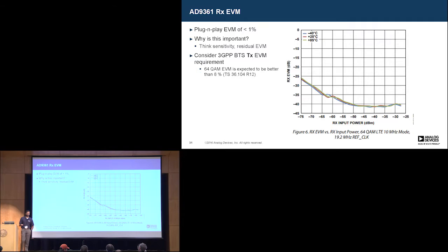The 3GPP specs, for example, call for a reference sensitivity level for different types of base stations. So for, let's say, 20 megahertz LTE, you have like minus 101.5 dBm that you need as a reference sensitivity level. And our customers would require even more margin to that spec. So you end up having to build transceivers that are going to beat any margin that you put in.